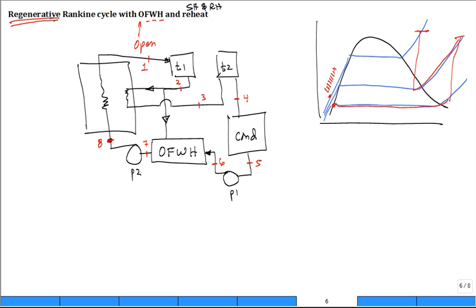So we look around in the power plant, we say, hey, there's some steam over there, it's very hot. Let's take a little of that steam to mix it with the feed water, and now that heating is internal to the cycle and not used. This temperature, from 6 to 7, it's much higher temperature at 8 and 7 than you could achieve without this open feed water heater.